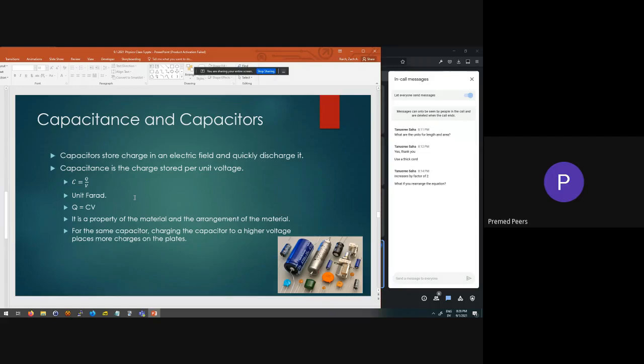That's it for resistors. Now for capacitors, which, again, have a lot of medical applications, which you'll see in the practice passage, and you'll also see in MCAT questions. So the point of a capacitor is to store charge. Batteries also store charge, but batteries use a chemical reaction. Batteries store voltage through a chemical reaction, and they're designed for long-term storage. So the voltage of a battery does not change very much as you use it. A capacitor stores voltage as charge across plates, and it's designed to quickly charge and quickly discharge, relatively quickly compared to a battery.